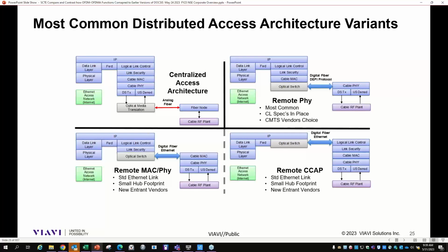That is the reason a lot of these systems are removing their digital video carriers and going completely all DOCSIS. That is a completely different change from what we've done for years. So analog carriers to digital video carriers to possibly all DOCSIS capability. And this infrastructure will support all of that as well.